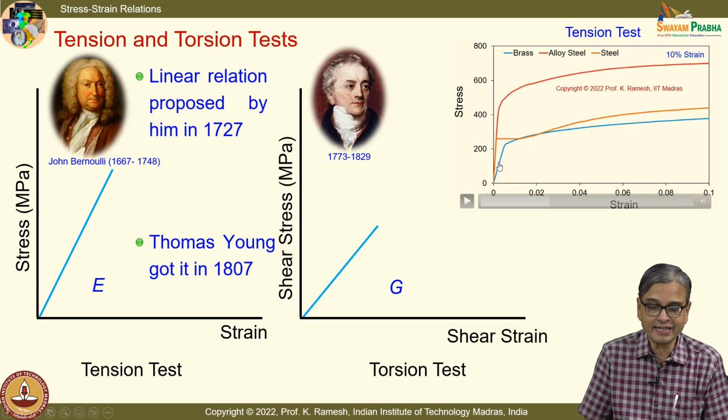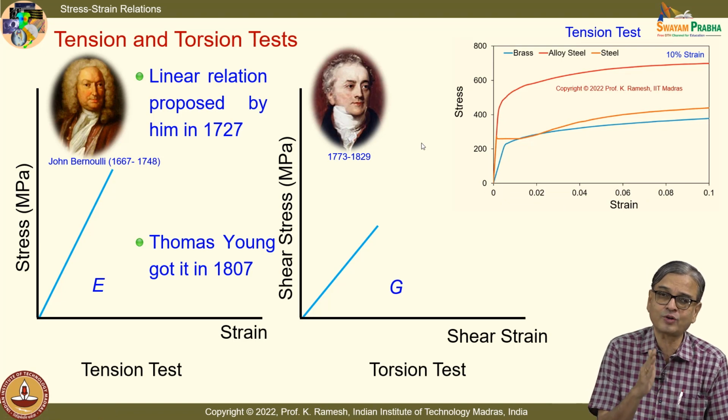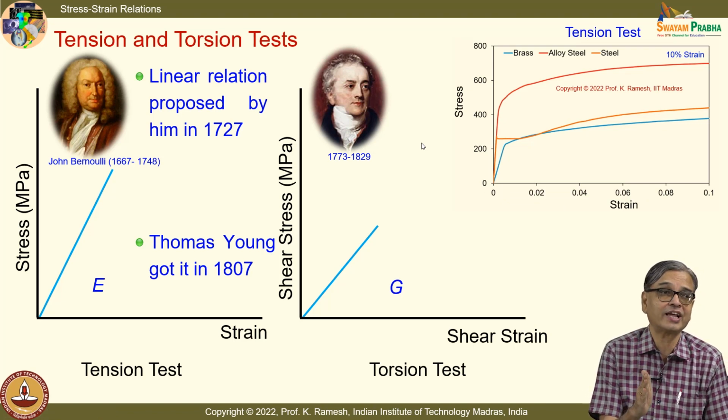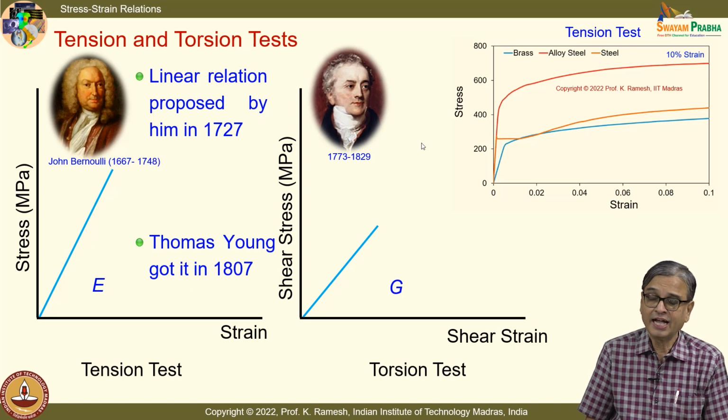If I have a linear elastic and a bilinear curve to represent the plastic region, you have it here. And if I have a straight line followed by strain hardening, it is there. So the only trick is you confine your strain to a very small value where you see all these simplified material models. They are very useful.